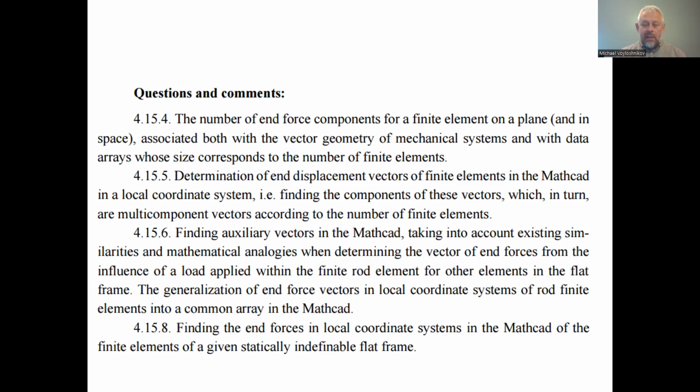And then, as well as in the finite element method, we used the beforehand decisions for the single span statically definable frame, when we can assign sometimes unit displacements for the statically definable single span frame finite element. We can have the unit displacement to define what the stiffness is, the force equivalent to unit displacement, for example, or the displacement equivalent to the unit force.